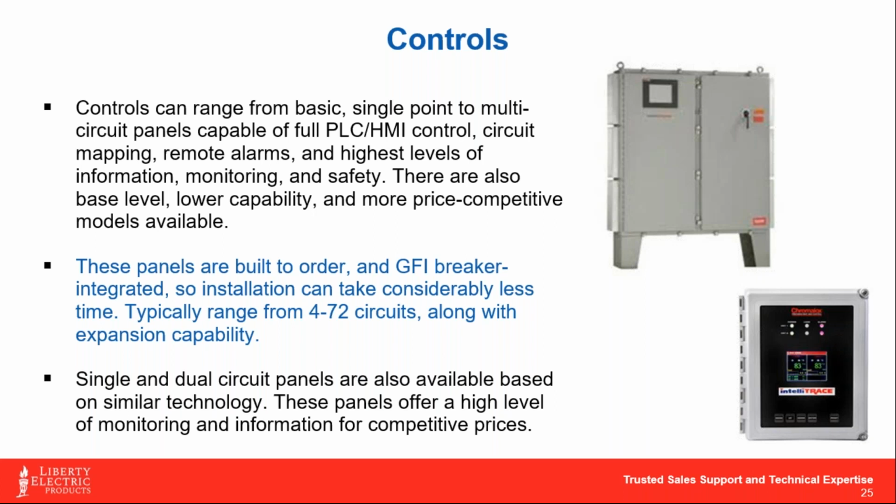They're small and compact. You can put them into pretty crowded situations, and glean a lot of information off them too. The nice thing about these automated panels is that typically if there's ever a fault, it tells you what it is, okay? And you can also get remote indication back to a BMS system, and so on and so forth. So again, these are usually a pretty good option from the standpoint that it cuts the labor figure down. The downside to the high-end panel is that usually they're a bit more finicky when it comes to power quality and things of that nature from within the plant.